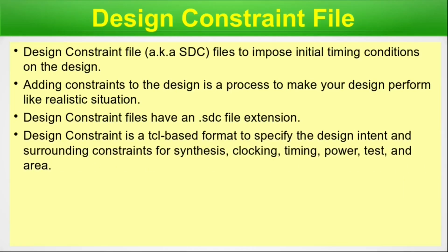Design constraint is a Tcl-based format to specify the design intent and the surrounding constraints for synthesis, clocking, timing, power, test, and area. This is a very important point. All the design constraint commands are nothing but Tcl procedures. In the Tcl series, I have already explained how Tcl works for VLSI. In case you have not watched that episode, I'll provide the link in the description.